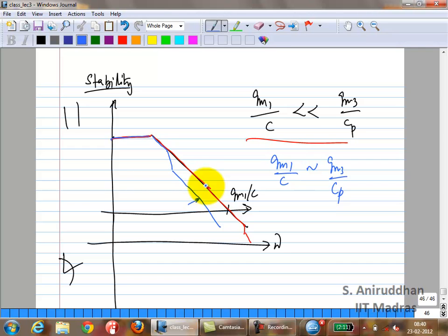Okay, so I want you to draw the Nyquist plot. I think we'll have it in the tutorial anyways. But you can show that if the magnitude plot crosses the 0 dB value at 20 dB per decade, the system is going to be stable. Okay, and you will see that the Nyquist plot will work out correctly also. We'll just take it for granted for now.